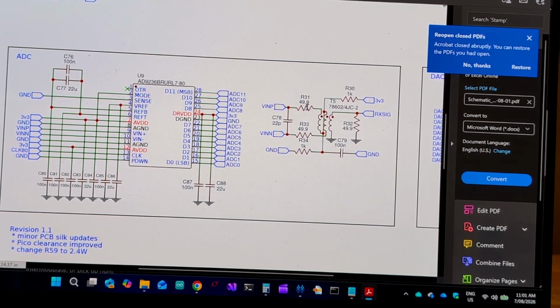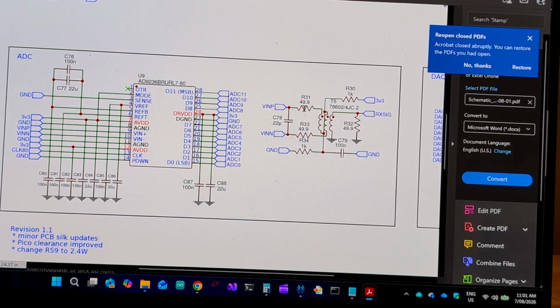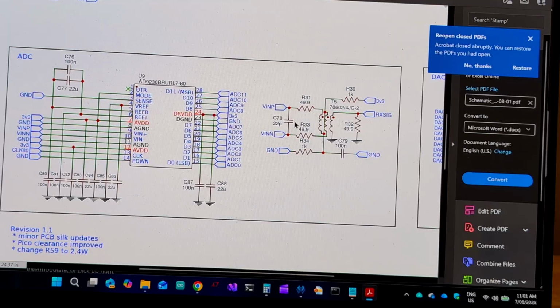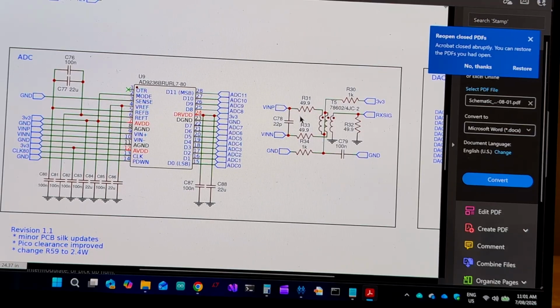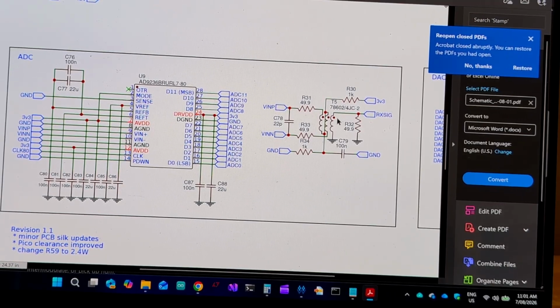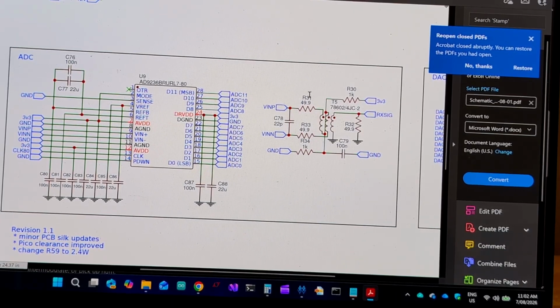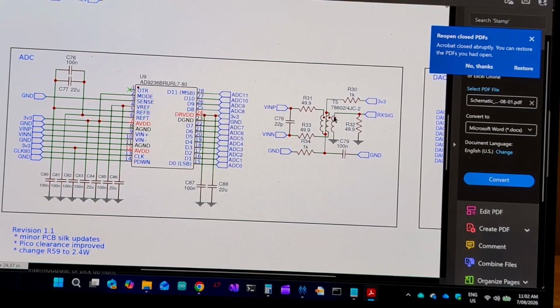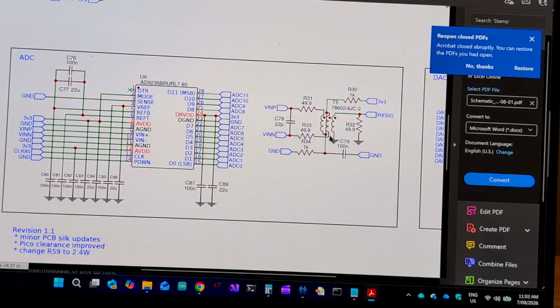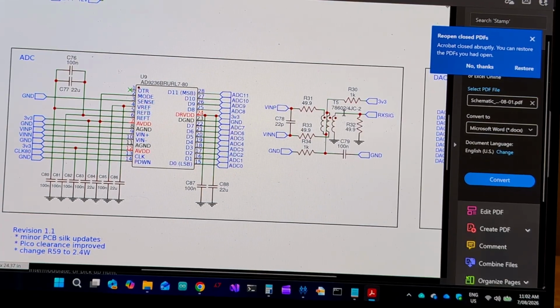Now, the 50 ohm resistors here, I just chose those so that you get a reasonable cutoff above 30 megahertz, and also it reduces the variance in resistors in the BOM. So this trifilar also means you can bias the input to half the supply rail.